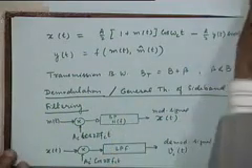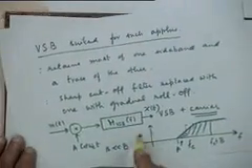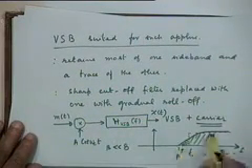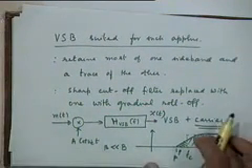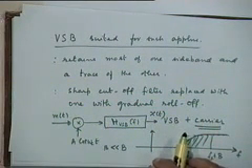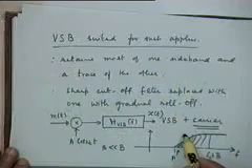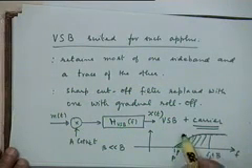The question is, you have some H(f) here, like the VSB filter, which has this kind of characteristic. We generally want this filter to have a gradual roll off, but the roll off can be designed in many different ways. Will any roll off be permissible, or only certain kinds of roll offs?